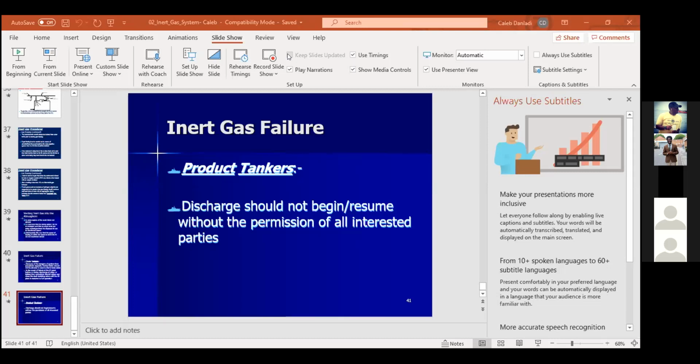So you have to have a very close collaboration between you and the shore. That is when you are alongside. But when they are supplying you, maybe after gas free, you are connected, you have control over everything because it's coming towards the engine room and you are the one sending it to deck. But with this one, they connect the manifold, they just send it to you and it goes in. So the terminal knows the requirements, the similar requirement. OCIMF is applicable to both of us, and you follow through.